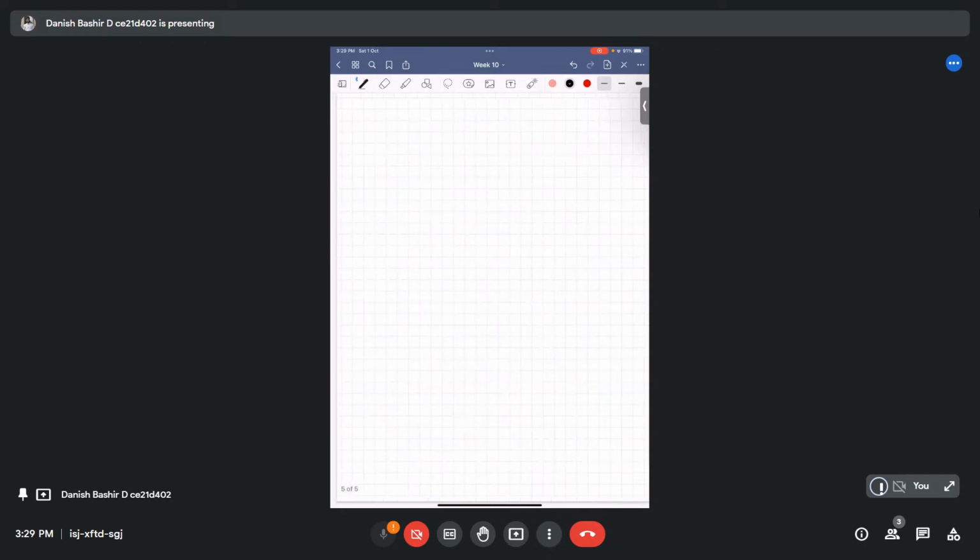First section will be loads on beam. First, from the projection, we can see that this is the projection. I already showed you 5 kilonewton per meter square. Remember, this is per meter square, and this width is 1 meter.